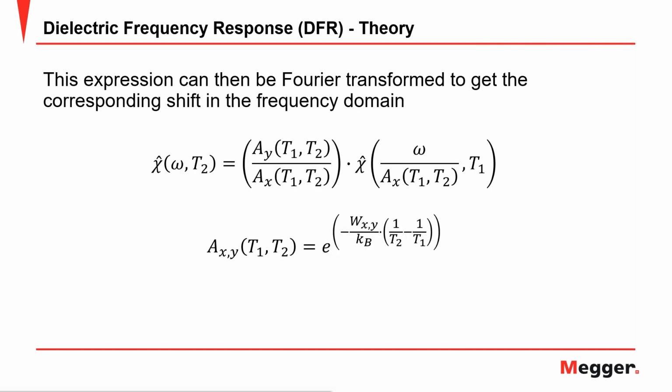And you can see here that we have the x-axis, the y-axis, and basically based on this and based on what is more important, which is the activation energy of the material, we can properly estimate based not on the reference table by nameplate, but on the condition that you have tested immediately, right, when you're running this test on your transformer.